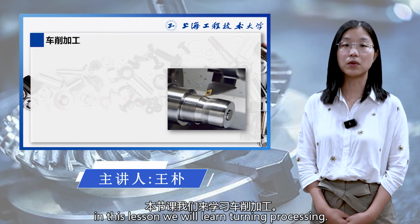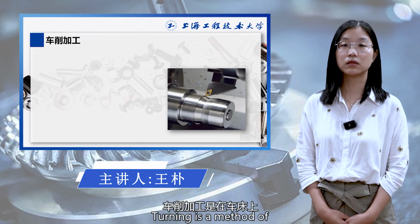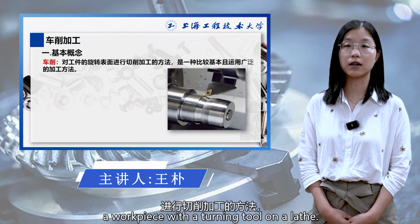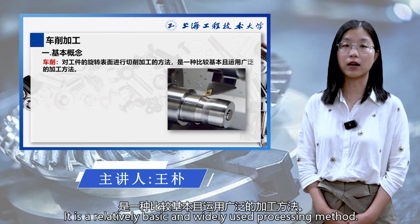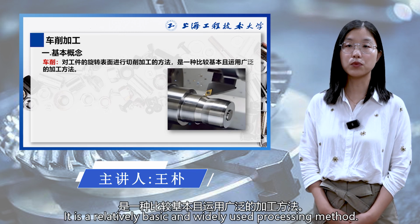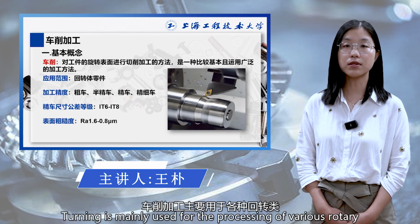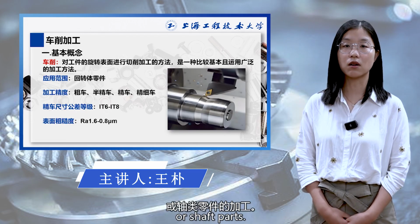Students, in this lesson, we will learn turning processing. Turning is a method of cutting the rotating surface of a workpiece with a turning tool on a lathe. It is a relatively basic and widely used processing method. Turning is mainly used for the processing of various rotary or shaft parts.